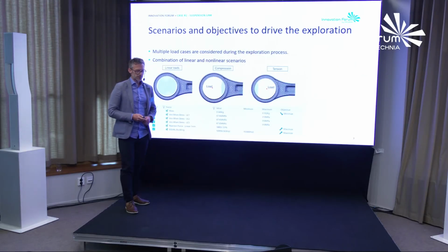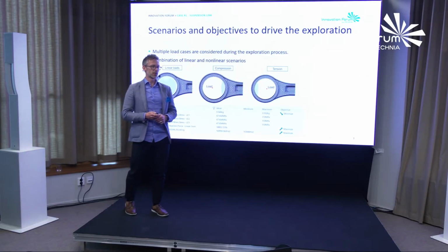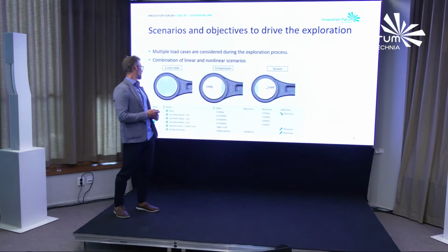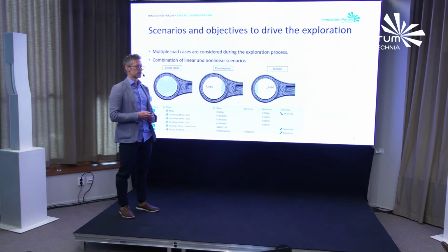The objectives, of course: mass, we want to minimize. Then we must make sure that we are under the stress or yield limit, so we check the stresses. And then we want to maximize the stiffness, so the reaction force and the eigenvalue buckling.